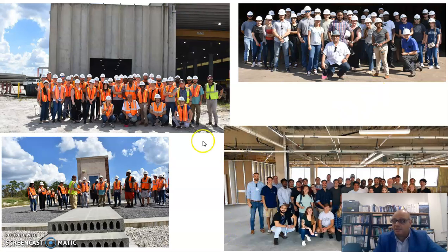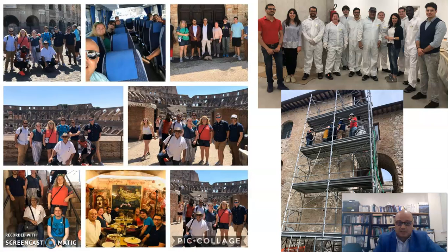I also used to, and I wish I was able to, take you guys on a field trip to GATE Precast so that you can see some components. Like this group of students that I have, we were able 2 years ago to go to GATE Precast to observe the construction of this hollow core slab. It's concrete, and we observed how they do this pre-stressing, like stretching the cables, and how they cast the concrete, and that was so good, and it adds to students.